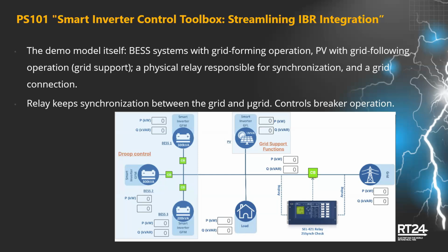Obviously, when the microgrid is by itself, not connected, it's running at its own phase, its own frequency, its own voltage levels. So when you connect it to the grid, there's the big challenge of how do I synchronize these two? It's quite difficult. There's a lot of control involved.